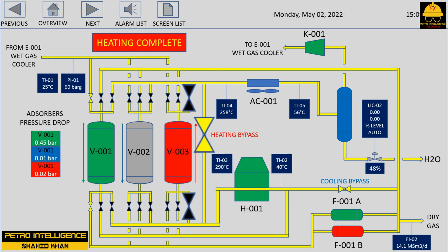In some cases, a step called classification of the bed is used. This is an operation in which flows are reversed through the bed, partially fluidizing the bed and loosening it up somewhat. At the same time, broken adsorbent particles and trash are washed from the bed.